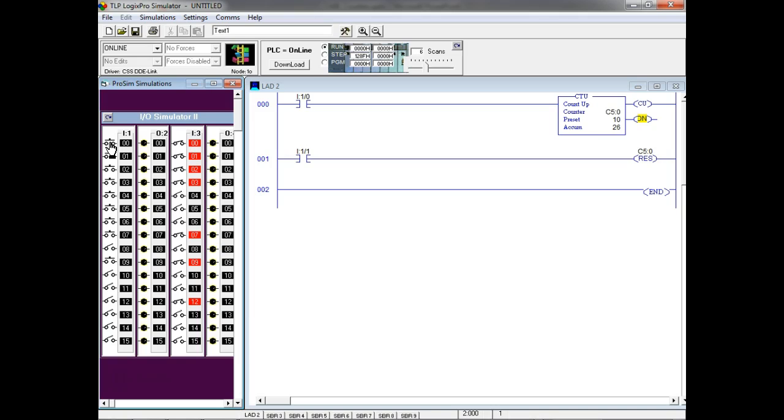So if I wanted to count a push button, I could count a push button, to keep track of how many times somebody hits the stop button every day to take breaks. But notice it keeps counting, right? Y'all see that? It keeps counting. Okay, and how are we going to clear it back? Notice the done bit is set if it meets or exceeds what? The count value. Y'all understand? Okay. And then I'll come back and I'll reset it.